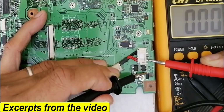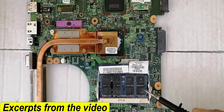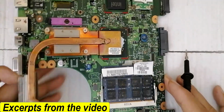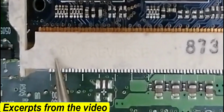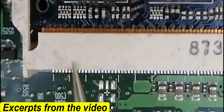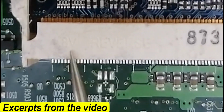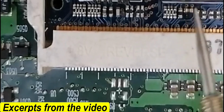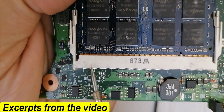As you can see, how can we identify the type of this RAM? Easy. We can just look here at the slot. Do you see the voltage here? We have 1.8 volts. Okay, 1.8 volts means this is DDR2, because the voltage for DDR2 is 1.8 volts.